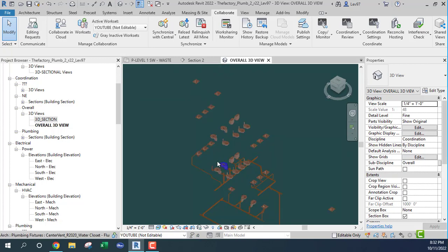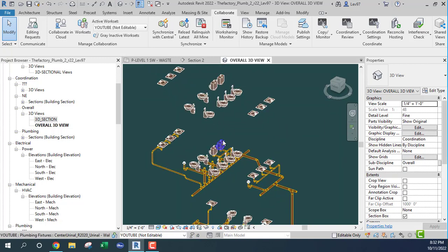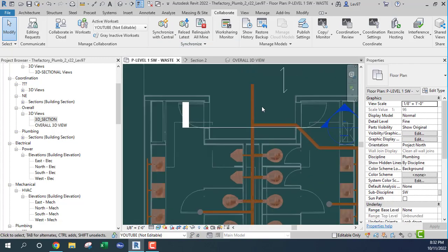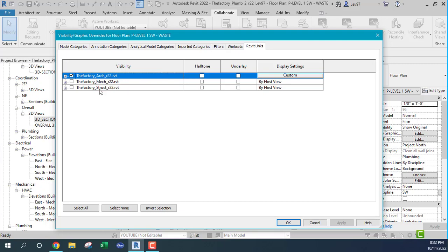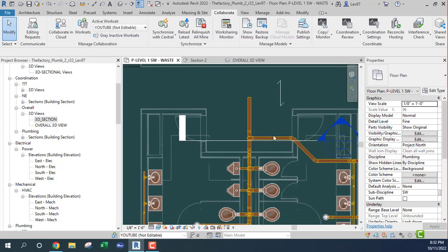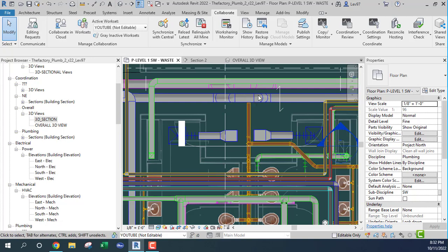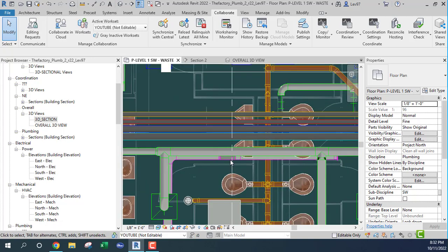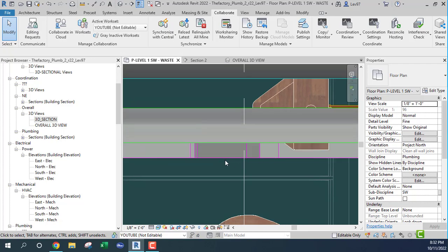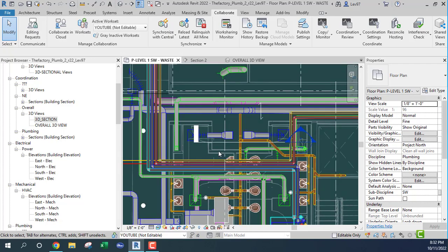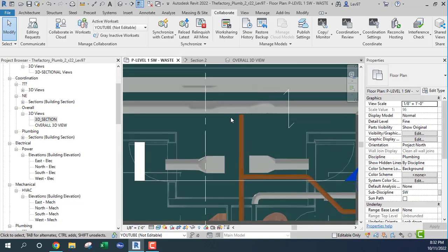So I would advise you to coordinate as soon as possible, just like when we were looking at this ductwork, right? And we had our mechanical interfering in here, where the changes were made here and the changes were made back here. I don't know if you can see that. There's an offset here. Okay. So once you note that these are interference, then you can immediately go to the mechanical, send an email, send him a cut sheet, or something that's gonna produce an image.